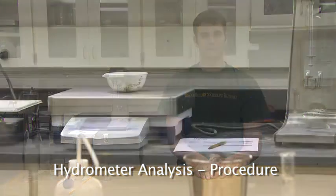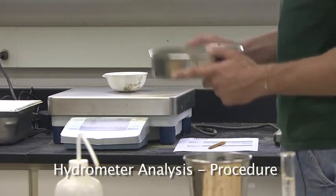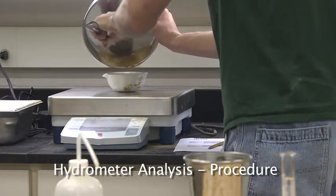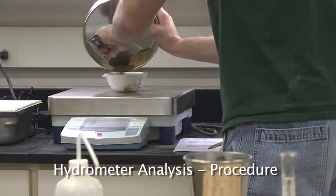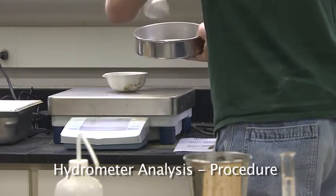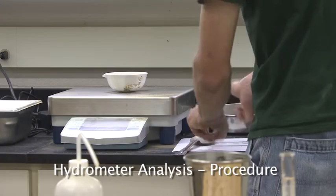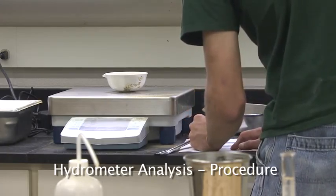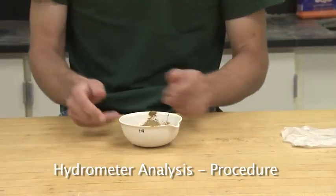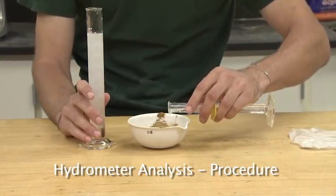The application of Stokes' law to falling spheres is used to determine the grain size distribution of the particles falling out of suspension. Start the hydrometer analysis by weighing out exactly 60 grams of the soil left over in the pan from the mechanical sieve analysis. Record the weight of the soil obtained on the data sheet. In a small evaporating dish, mix the soil with 125 milliliters of 4% sodium hexametaphosphate.